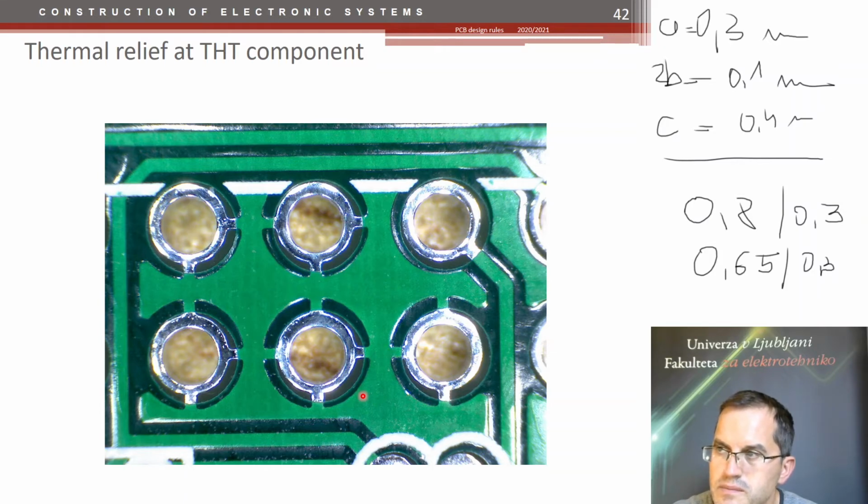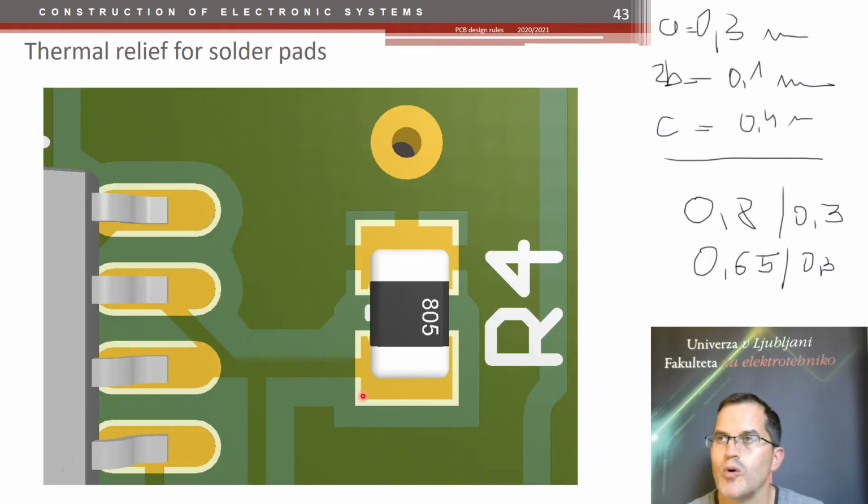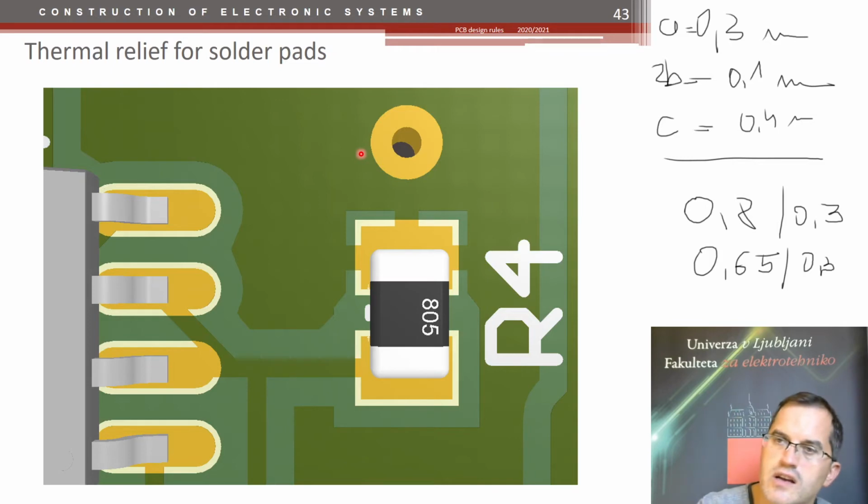Now, what about SMT pads? The SMT pads also have to use thermal reliefs. And still, look at this image here. This pad is connected with a single line, and this pad is connected with 3 lines. And here is a wire. Okay, let's check out what can happen.